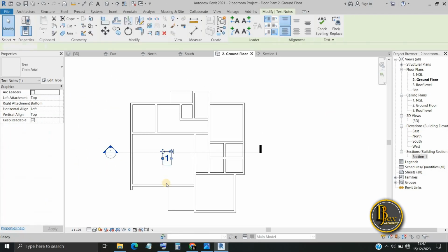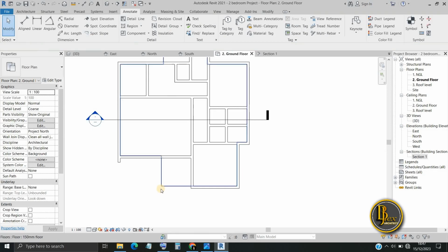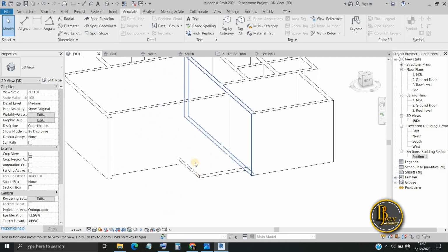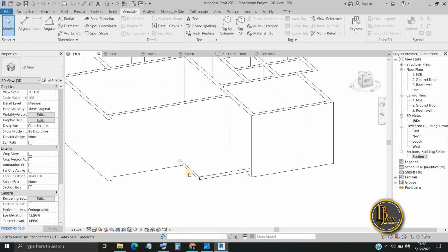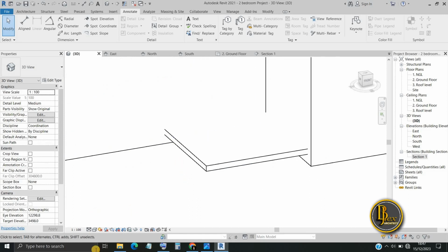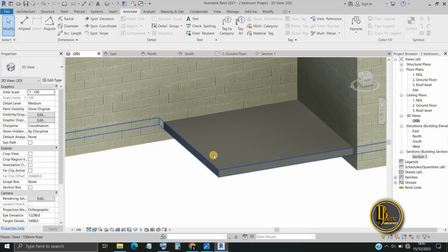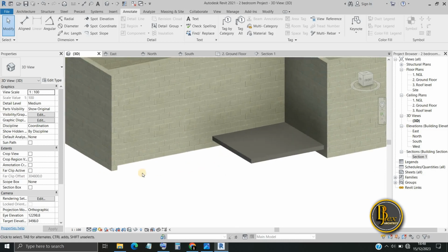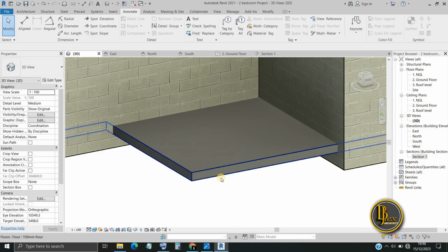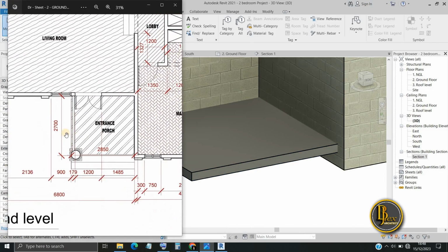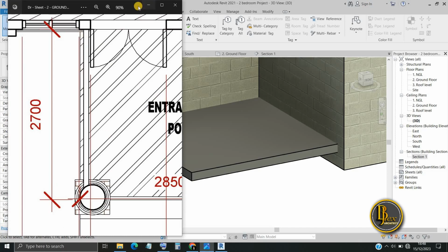Let's delete this annotation. So now if you look at this floor on your 3D, it's looking way better because we copied it well from the other side to this side. But now there's a vacuum space somewhere here. If you look at your realistic view, there's a vacuum space here. This doesn't look right. Your floor is not going to be floating on the air. So we are trying to put a dwarf wall somewhere here. Then this place will leave the staircase. This place will be covered by a wall, so that we'll hide this.